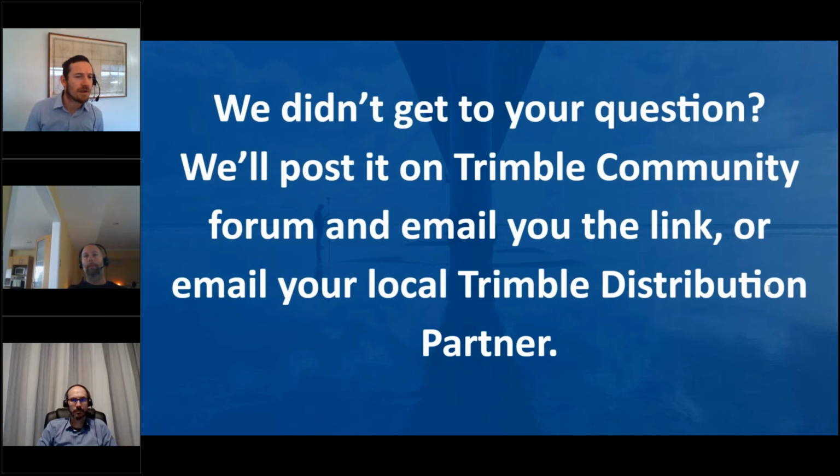Yeah, anecdotally, I've gone out and done a little bit of checking just on the VRS Now correction over IP, and it wasn't any points that were particularly accurate. I was just down at the local park near me, measuring the corner of a cricket pitch, which is covered with that fake grass, so it's not very exact, and I'm sure I wasn't on the same point each time. But with the RTX correction coming in, no bipod or anything, I was staking out and getting between 0 and 15 mil on the corner each time. So it does seem pretty consistent.